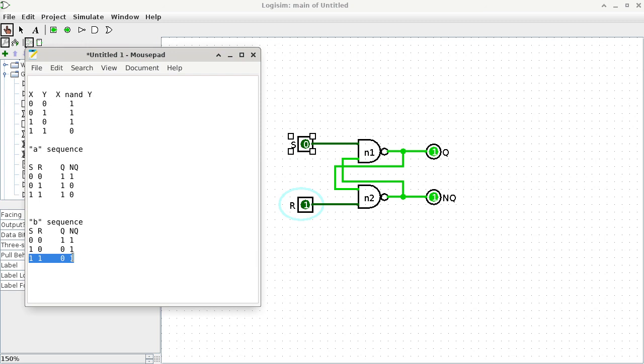Does everybody understand what I'm trying to emphasize? It remembered. If you make both of them the same, it'll keep the previous state. Exactly. Yep, that's exactly what is happening here. When the input pins are both ones, it is basically saying, just maintain your previous state. Unless the previous state is having both inputs being zeros, that would be a bad thing because that starts the oscillation.